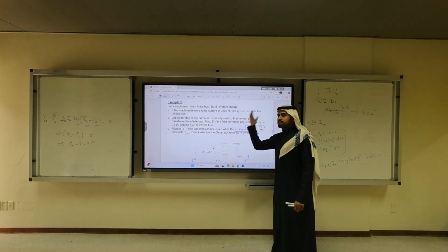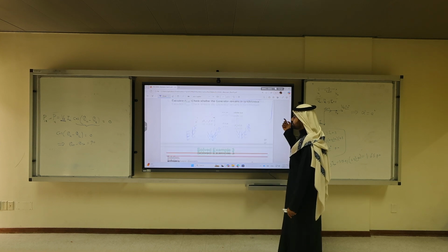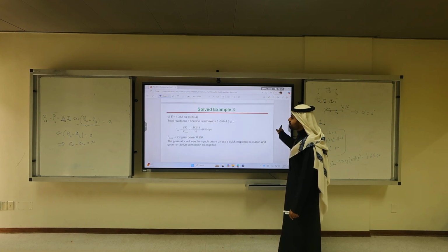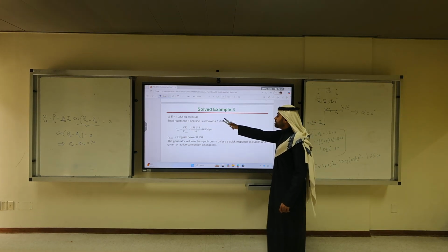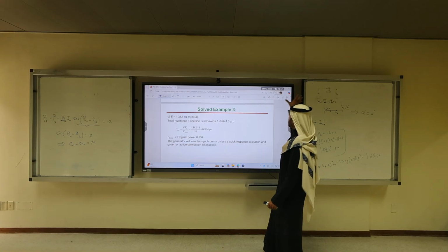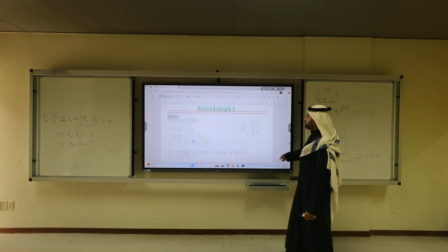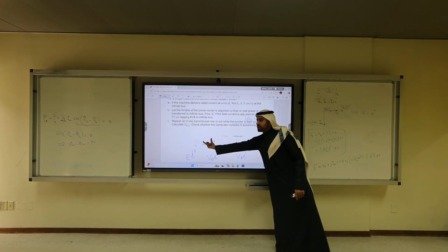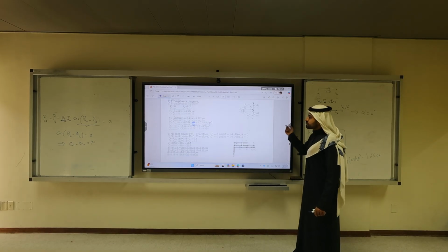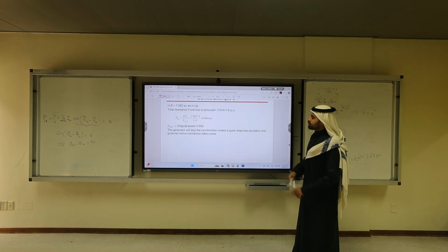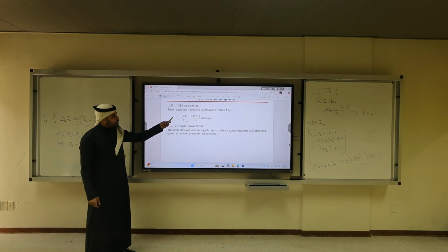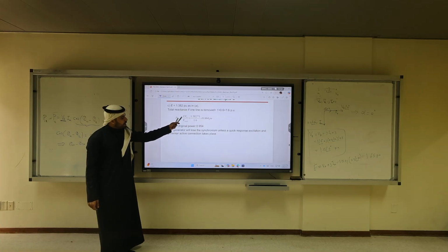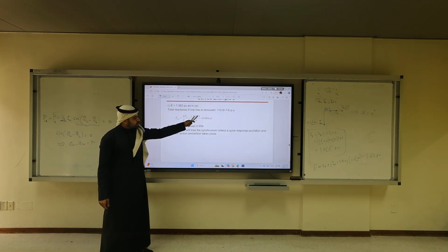So if you're keeping the excitation at the level of part A, and you lose one transmission line, are we in a stable region or not? That is the question. So here, how he solved it is: the total reactance of the system is 1.6 per unit, because you have 0.6 here, 0.6 here, plus 1. The maximum real power transfer is E, which is 1.382, times Vb, which is 1, the infinite bus, over the total reactance, 1.6.